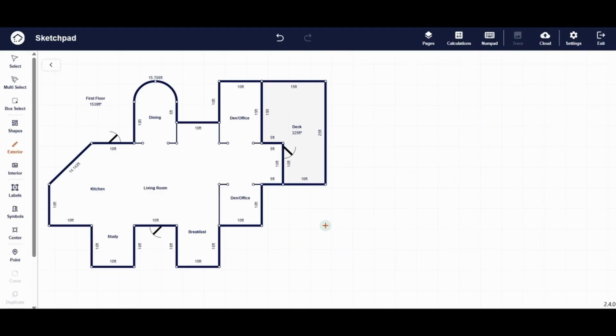Okay, so I'm at this alignment point. I'm going to now type in 10 on my keypad, or what we call numpad. If you look at the lower left hand corner, you see the 10 over there. Okay, and I'm going to press the right arrow. Okay, so now I jump 10 away from that wall, or 25 from the bottom wall. But again, I was lined up with the upper wall over there. Okay, so I'm perfectly lined up with that bottom wall, and I'm just offset by 10.